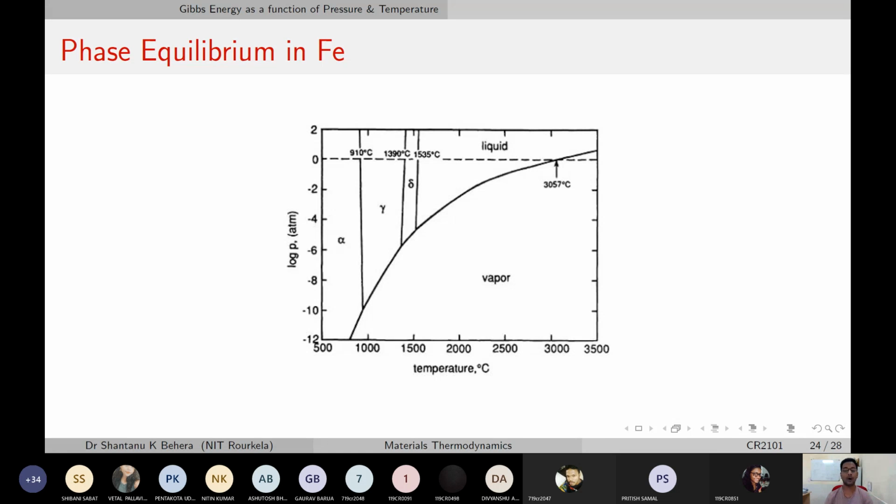But when you talk about appropriating what is exactly there in the unit cell, you see that there's one in the middle and then 1/8 of each of the corners. That is the share of the cube that you're talking about. So it's like two atoms per unit cube. Okay, so that's the BCC phase. So this alpha iron is actually the BCC iron.